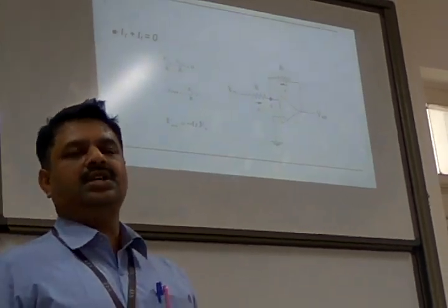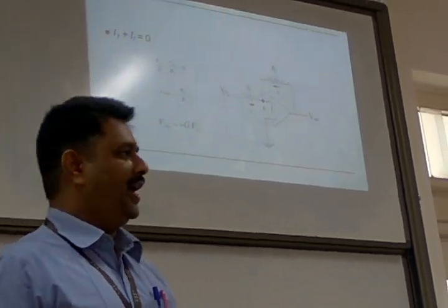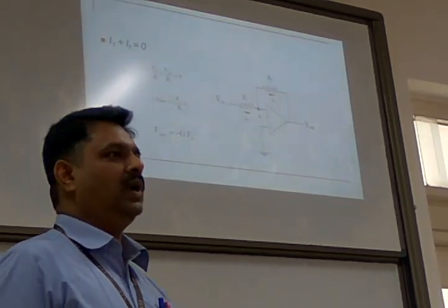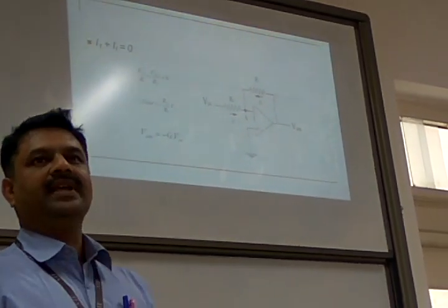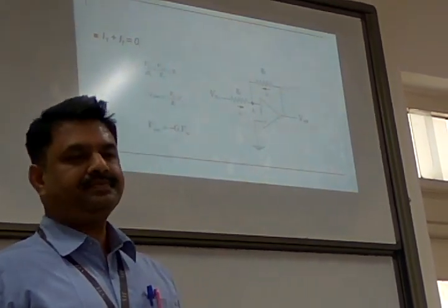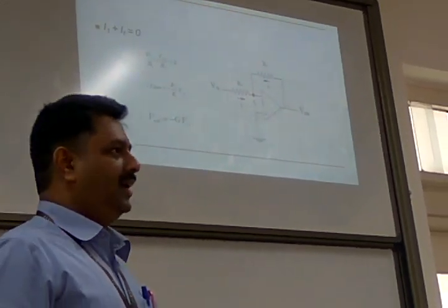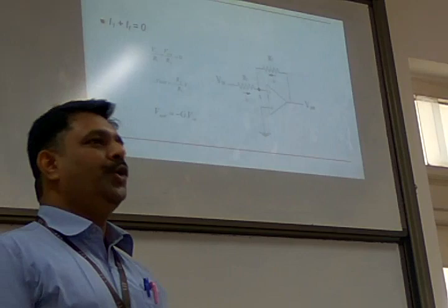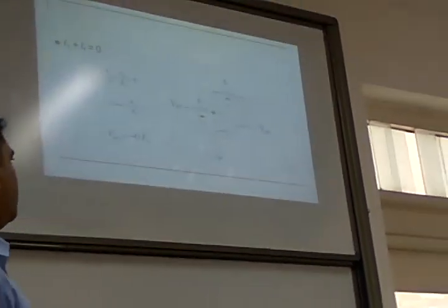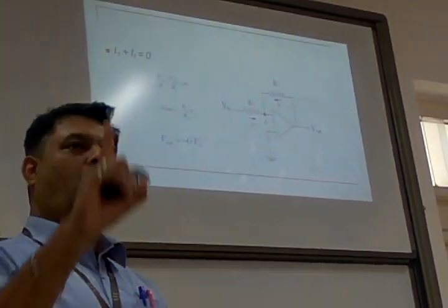So it simply follows. Such devices have many names. One is voltage follower. Whatever is the input voltage, the output voltage follows, so it is voltage follower. The other name is buffer. Also it is called unit gain amplifier. It doesn't have much gain, but it is a unit gain amplifier. Like that, you have various names if the device gain is equal to 1.